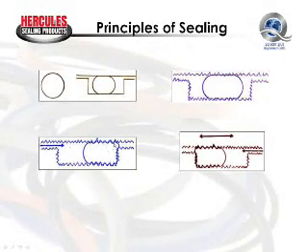If we have a static sealing application, we have flow from one direction. The flow pushes the O-ring to one side of the groove. When we have a resistance to flow, we have an increase in pressure. The greater the pressure, the greater conformity to the sealing surface, and it reduces our leakage path. This is the scenario we have with a static seal.